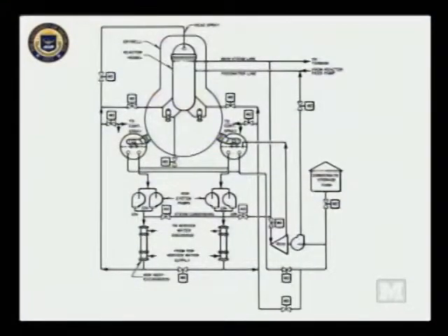So within several hours to a day, I do not have the exact sequence, there was overheating and uncovering of fuel element. As a result, the zirconium cladding reacted with water, and it's an exothermic reaction that produces hydrogen. So pressure built up inside the reactor vessel, and some of the hydrogen mixed with the steam was vented into suppression pool. And again, pressure is building up here.